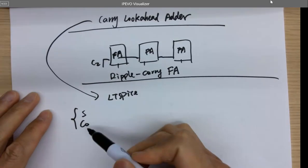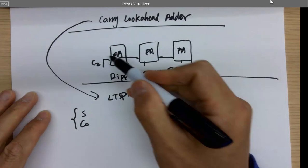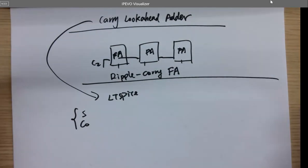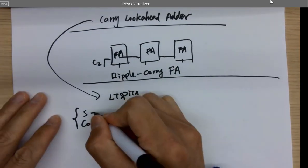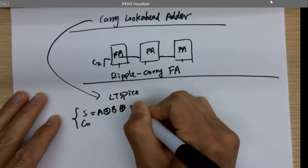For the logic of the carry look-ahead adder, it's not changing the full adder's nature. It's still a full adder, so the logic is the same. S equals A XOR B XOR CI.